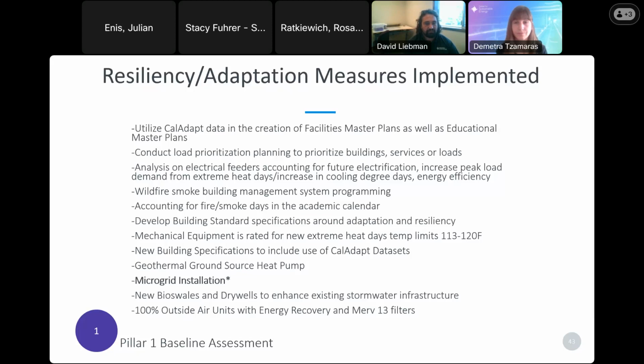on how to utilize that data. Another example includes how to use high intensity rainfall in stormwater infrastructure management to prevent flooding. Most of the data is not utilized for flood protection. When it comes to stormwater infrastructure of civil engineers, it's mostly done for how to treat water on the first inch of rainfall to prevent it from going into creeks and rivers, which is important. But now we're seeing another need: how do you adapt and design stormwater infrastructure for the high intensity rainfall that's projected to occur in a short period of time.